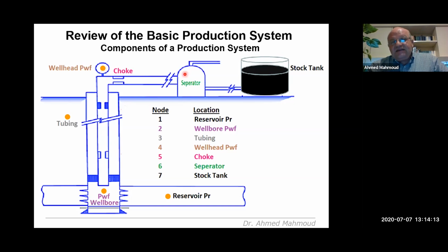Now, my next trip is going to be to the separator, and because the separator pressure you can adjust to be lower than the wellhead, obviously the flow will come from the wellhead into the separator, and then finally the separator pressure will definitely be higher than the stock tank, and the entire loop takes place, and the whole thing is initiated by one piece of magic called delta P.